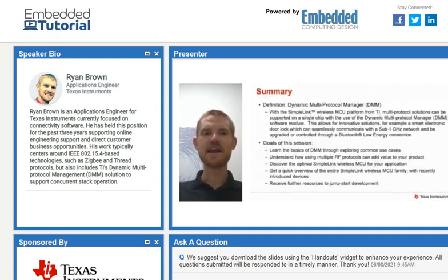So what is the Dynamic Multi-Protocol Manager, or DMM for short? Well, with the SimpleLink wireless MCU platform from Texas Instruments, multi-protocol solutions can be supported with a single chip using the Dynamic Multi-Protocol Manager software module. This allows for innovative solutions. For example, combining a Bluetooth low energy connection with a sub 1 gigahertz network. Therefore, you're able to commission and control the network through Bluetooth low energy, but communication is accomplished over the sub 1 gigahertz network. We'll go through several examples later on to demonstrate how this is accomplished.